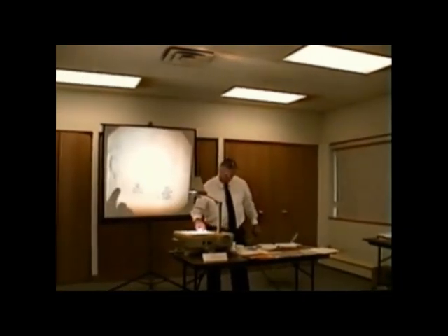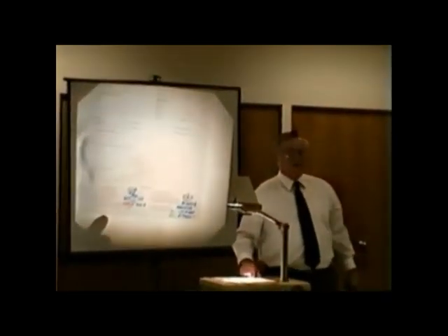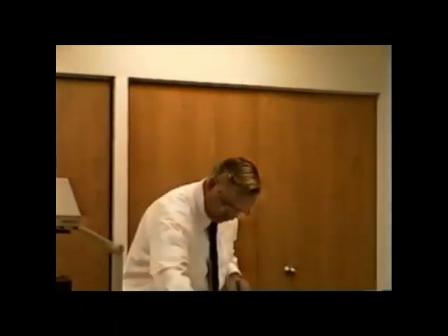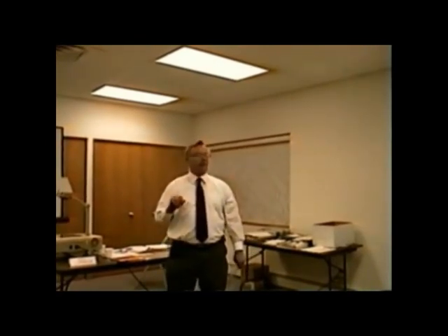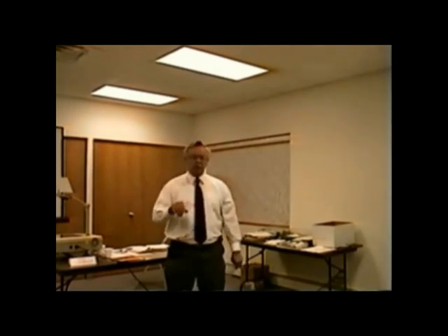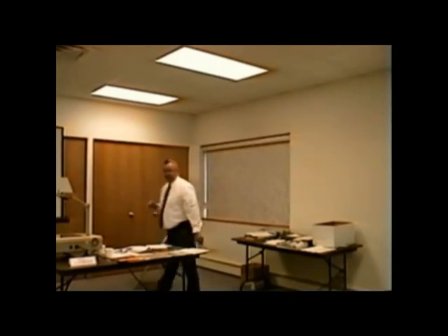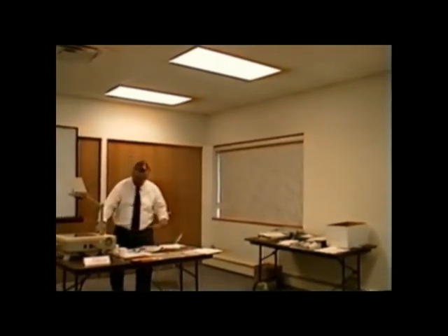And so at this point here, look at this, ladies and gentlemen. We have answered questions 1 through 13. Okay? Oh, by the way, when you do a temperature rise, I want to make something very clear. Let me shut this off and we'll talk here real quick. When you do a temperature rise, that furnace must run for 15 minutes and not limit one time. That 15-minute run time is part of your 20-minute diagnostics. Because while you're heating it up or whatever you're doing, you're checking gas pressure, you're checking flame sensing, you're cycling the gas valve, and so forth. So again, I hope I've made that clear that it cannot limit one time. Otherwise, we have an overheating furnace.